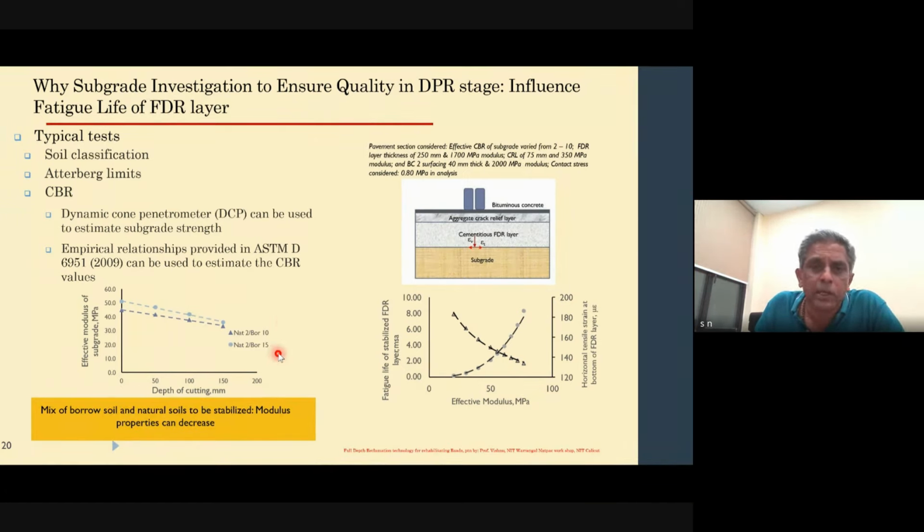Either it can be depending on the road that you actually see. If it is damaged along the outer wheel path, then it's good to have a sample collected there and something outside of that as well, so that the uniformity is maintained as you go along in terms of your sampling. Now, along with making trench pits for collecting samples, it's always a good practice to have multiple trenches.